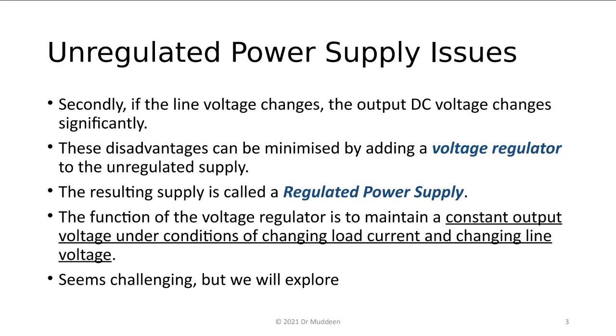If you remember from your digital electronics, when you were talking about voltage levels, for instance, if you're talking about a 5 volt DC logic level, there was a voltage of 5 volts and a short range below that is considered a 1 or high, and then there's a voltage close to 0, somewhere between 0 and maybe 0.7, 0.8, or 1.2, depending on the particular device, that is considered a 0.